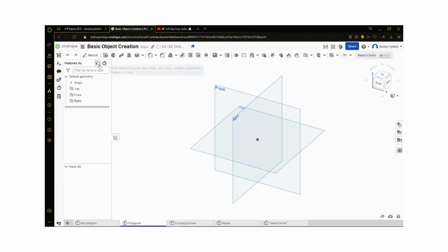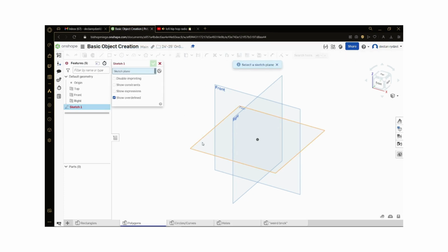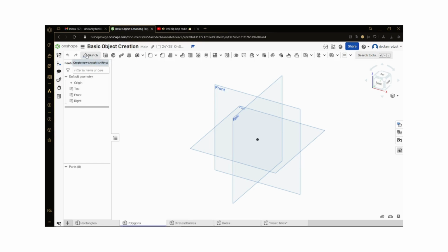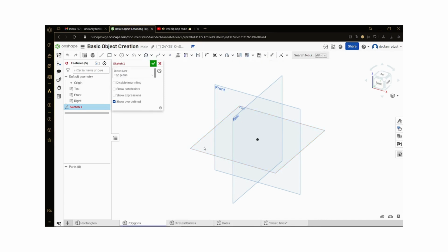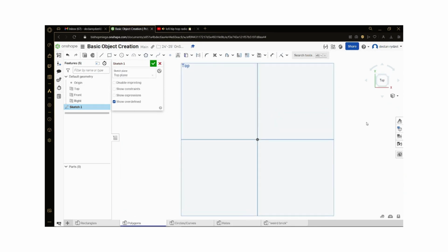Next up is another pretty useful tool for making all sorts of shapes. It'll be the polygon tool. So going up next, do the same thing that we did before. Click on the sketch, click a plane, center yourself, and then over here is what is called an inscribed polygon tool, or just the polygon tool. And what you do is you click on the center, or where you want your shape to be centered, and then you do that, and it brings it out.